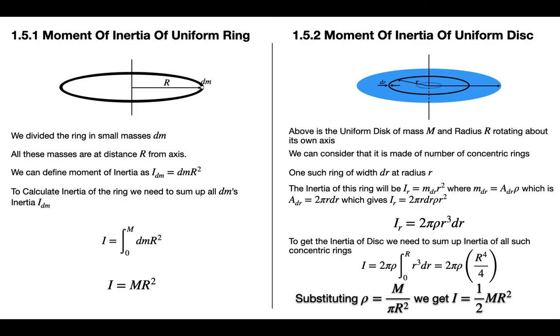If you compare the inertia of a uniform ring and a uniform disk, the m is the same, r square is the same, but in a uniform ring most of the mass is at the distance r, so inertia is also located around that r. In a uniform disk, it shifts a little bit inward. That is the difference you have.